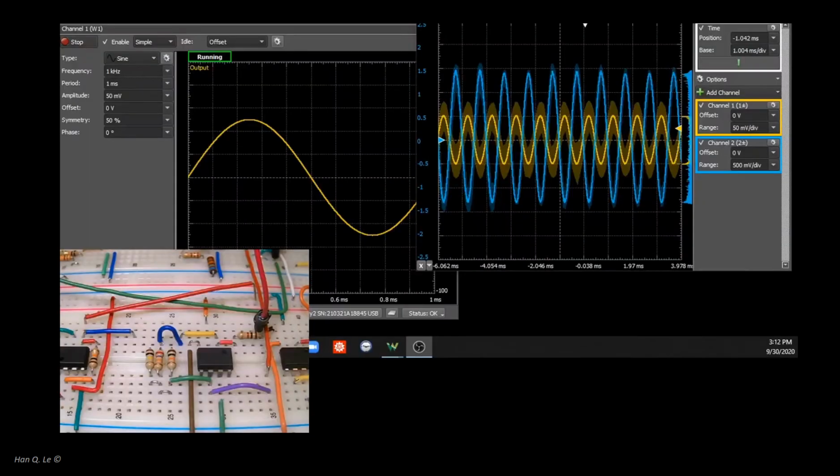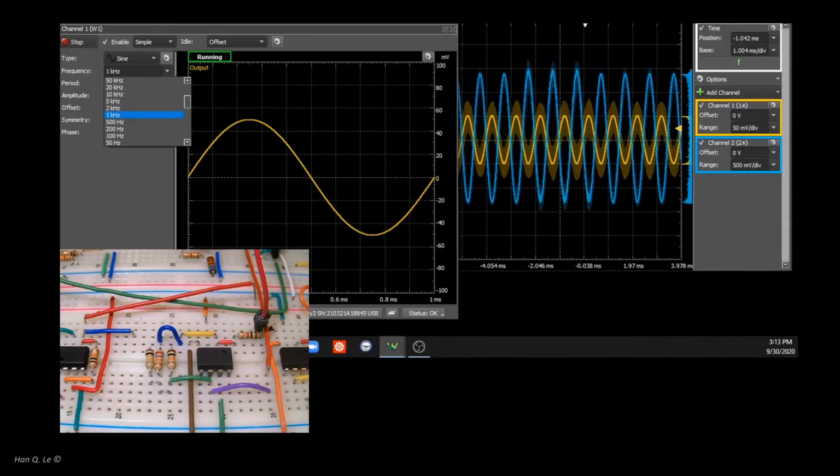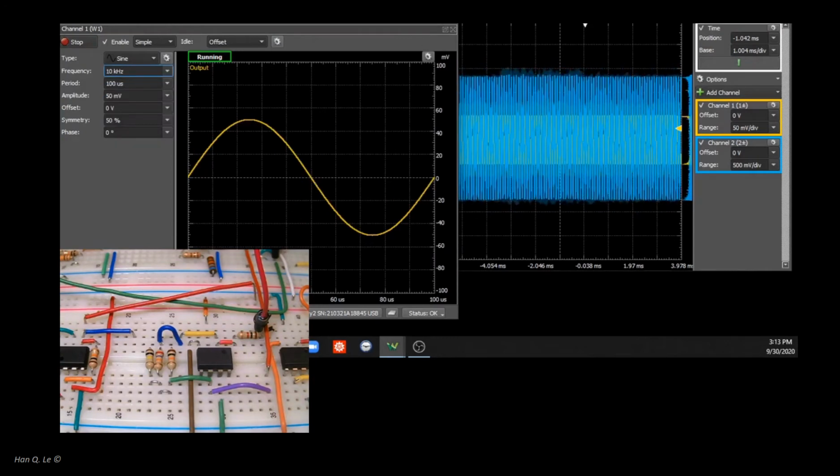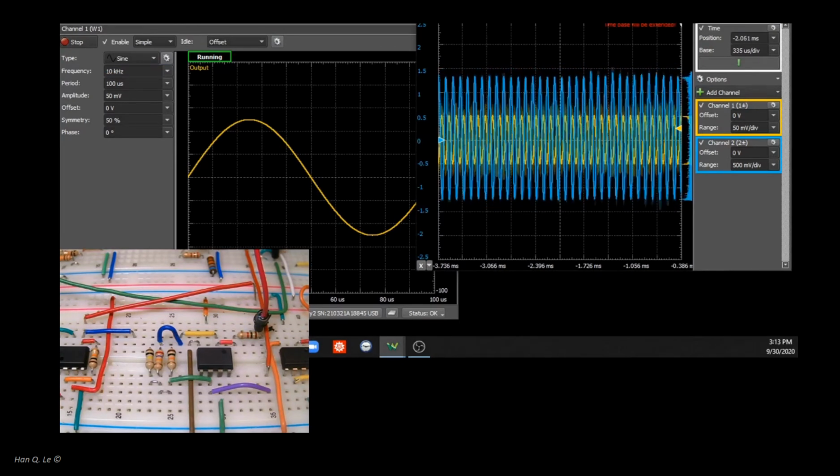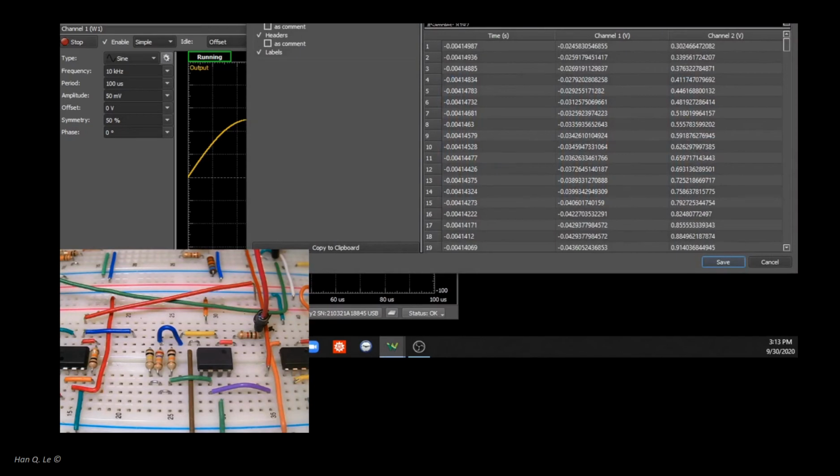The following shows an example of a typical measurement. The input signal is set up with desired properties, such as frequency. AD2 data length is about 8000, select the time base such that there are roughly 32 to less than 256 cycles in the displayed scope trace. Then hit Export button, select CSV format and save.